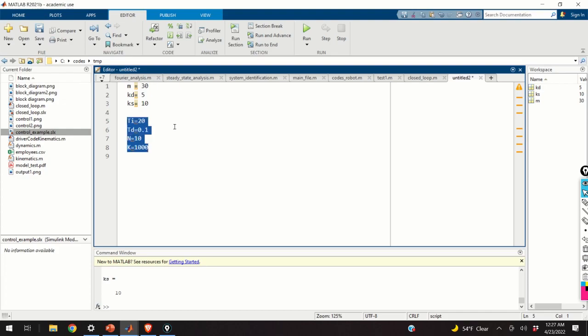Watch out here, I selected these parameters by tuning my PID control algorithm. You can initially select a large proportional gain and set some of these values to 0 or to large values in order to eliminate either derivative action or integral action. However, for the time being, and in the interest of brevity of this video, I keep these parameters as they are. Okay, and let us evaluate this such that we avoid the warning messages.